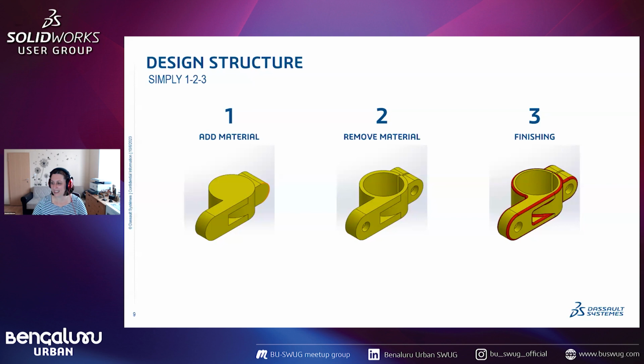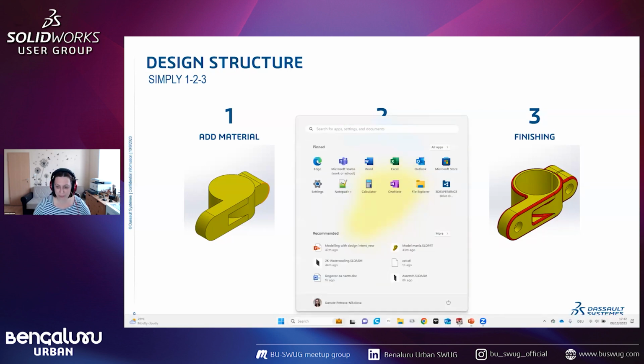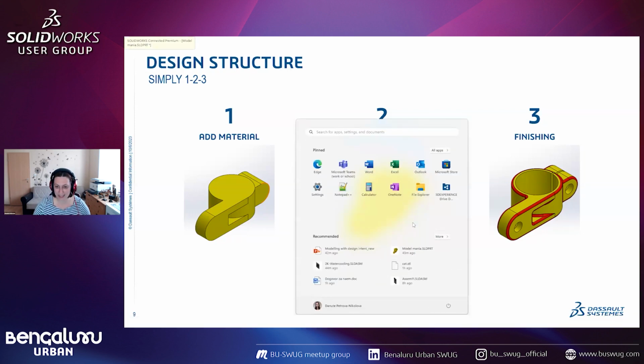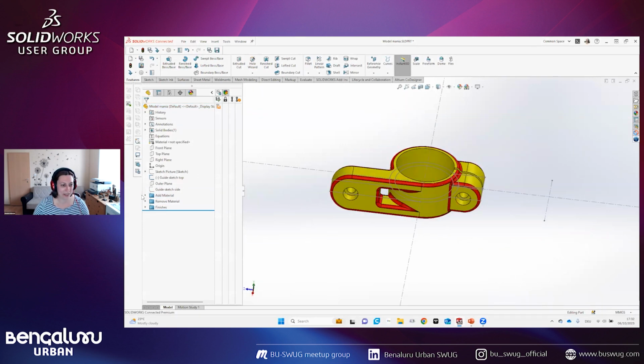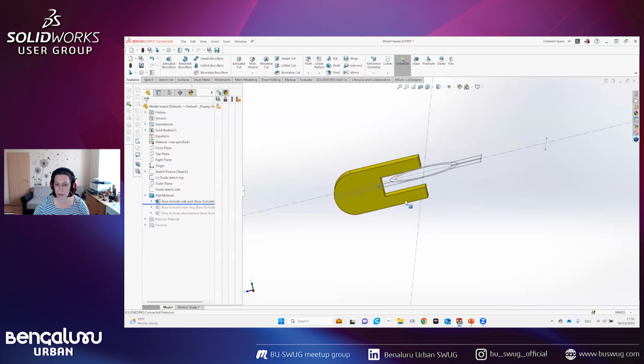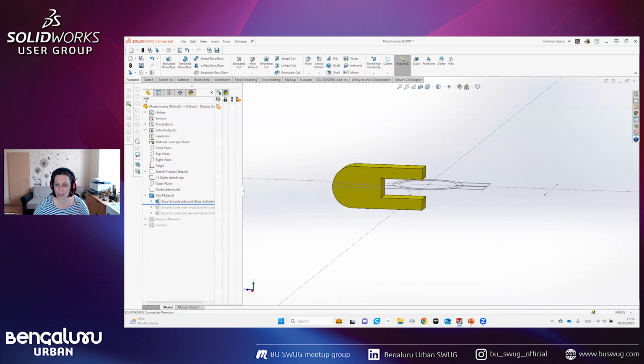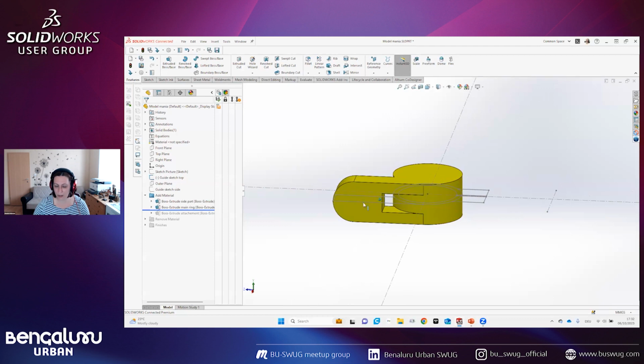We have one question from Abhishek. He wants to ask how you created the cut in the middle. Does he mean this cut here? Yeah, okay. I'm guessing the first cut, not the circular cut, but yeah, that. Yeah, this one. That's a good question. In this particular case, I made a boss extrude first with the cut directly inside, and then I made the other boss extrude.